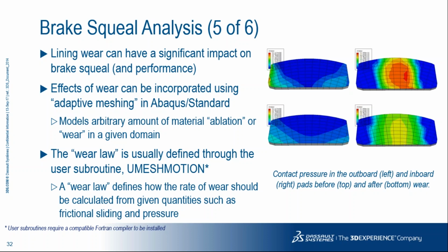Similarly, finite element analysis using an unworn lining profile can generate an unrealistic contact pattern that causes discrepancies in noise prediction. Abaqus Standard adaptive meshing and adaptive mesh constraints can be used to model an arbitrarily large amount of ablation of material away from the domain.